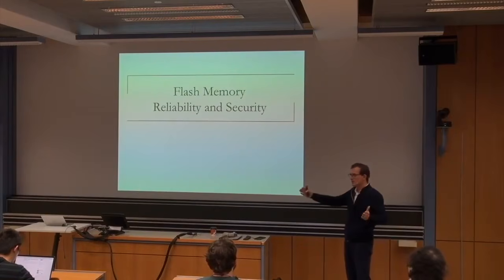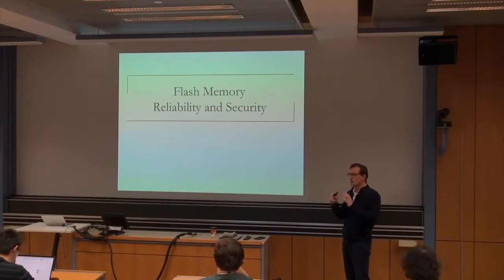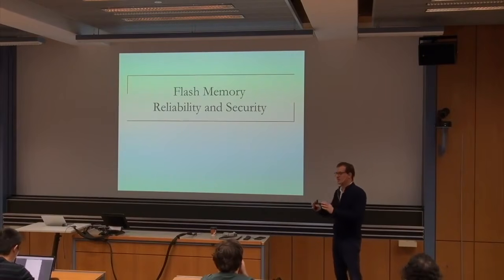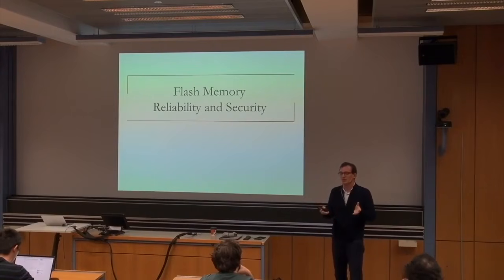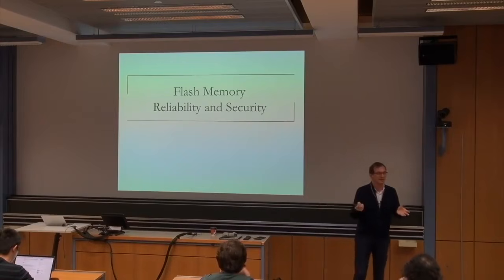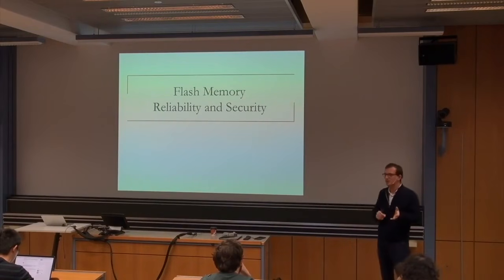So if you want to write to a location, change the value of a page, it's not easy, right? As we've seen. What do you do? Because let's assume that you have read this page and that you modified the contents of that page. Now you need to reprogram it. Reprogramming it is not easy because you cannot just write to that page, because when you want to actually reprogram, you only can increase the voltages. If you want to decrease the voltage, you need to erase it.